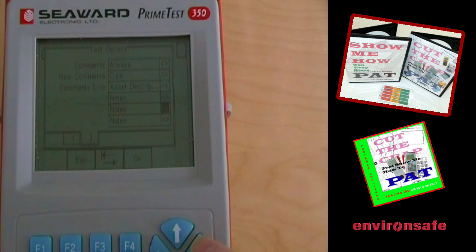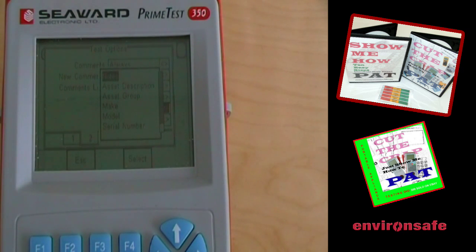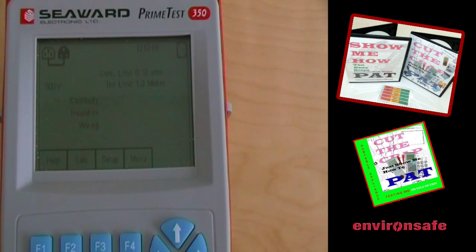And you can scroll down, as you can see the next one is the same. So those choices you can make. If you're using PatTest software, it's important to make sure that how you list the items here is exactly the same as you list them on the software. Otherwise you'll have configuration problems. Press F2 to escape this menu. F2 to escape again.